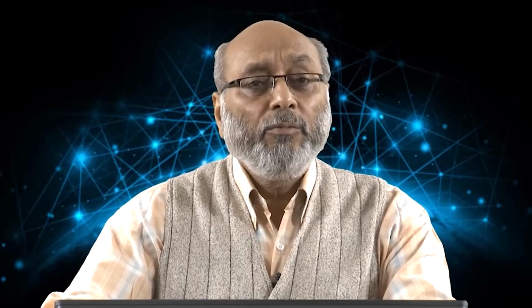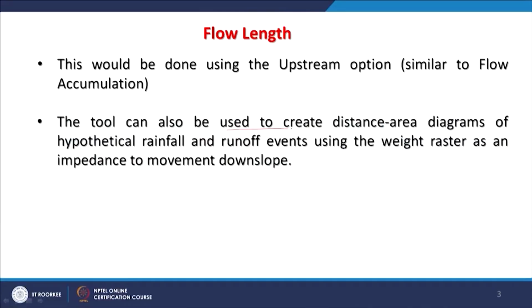This flow length will be derived using the upstream option, similar to flow accumulation, because it is sequential processing in surface hydrologic modeling. So this is basically the fifth step in surface hydrologic modeling. This tool can also be used to create a distance-area diagram of hypothetical rainfall and runoff events, using a weight raster as an impedance to the movement down the slope.